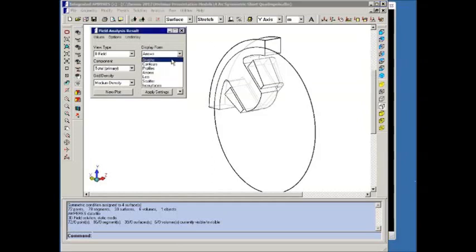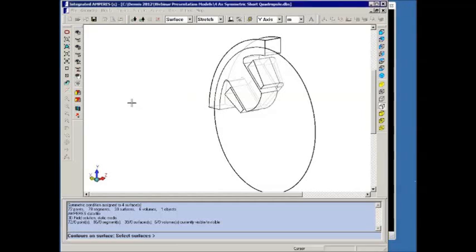So now I'm going to plot very coarse contours of the vector potentials. This is equivalent to the field line plots that we do in Magneto. What you do is plot the normal component, and in this case, the way the plane is oriented, the normal component is actually the z component. Sometimes you have to use the normal component calculated on the surface, but in this case we can just plot the z component. And now I'll just select, you notice here I'm selecting the surface. If I select up here, I'm selecting that pole, but I want this whole circular surface.